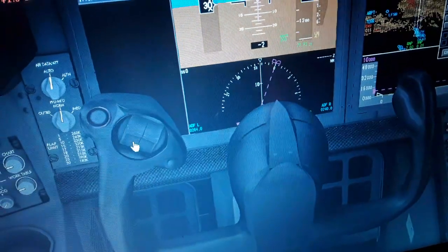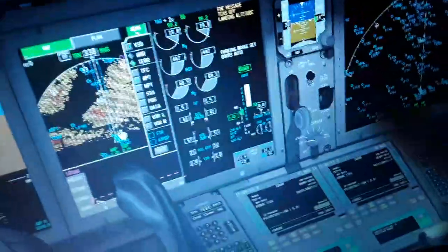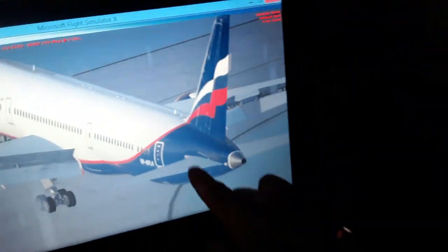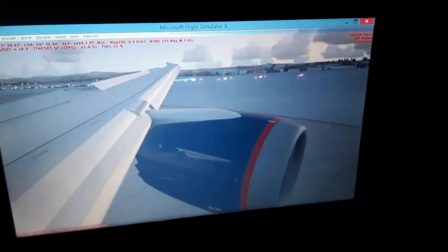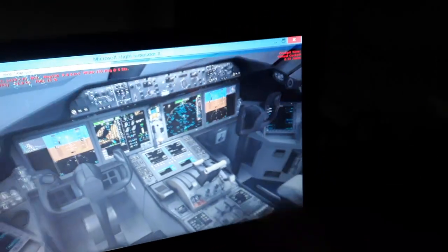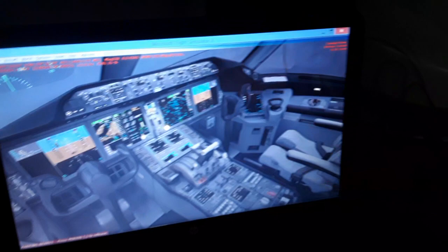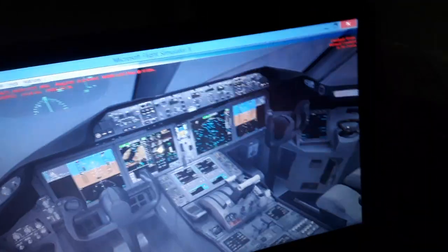You also use the manual trim all the time here on the control wheel, and you see it displayed here, and you can see the elevator trim over here. You will move the elevator up and down. Also, as you move the side stick or the yoke of your aircraft, flying either Airbus or Boeing, you can control the elevator trimming. Some aircraft have the elevator trim wheel here, the older models. This one has switches because it's a newer model.